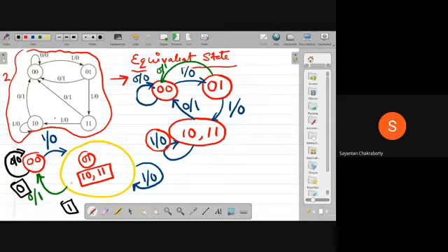So this reduction in number of states shall not always translate to a reduction in the design complexity. In some situations, it will become very, very complex, involving a lot more logic gates. The requirement for flip-flops will be reduced, but the logic gate requirement will be much more. But the advantage is that the principal transitions can be found out very easily. These are the principal transitions that can take place. Or the pictorial representation will be much, much more concise.